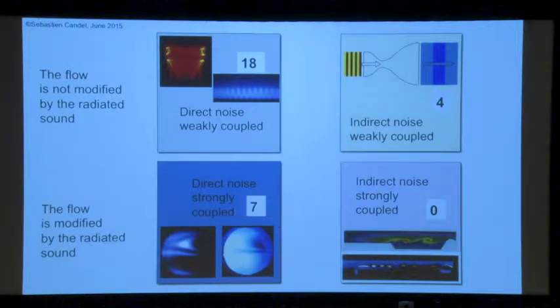You have a system which is synchronized by this cavity, and you get very low frequency in this case because these are very large boosters, and they vibrate because of this mechanism of vortex shedding in solid rocket engines. So it's indirect because it's vortices, with no pressure field fluctuations, impinging on a nozzle and producing a pressure field. The pressure field synchronizes the vortices.